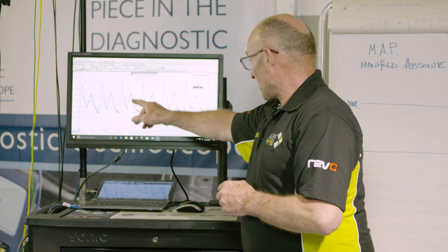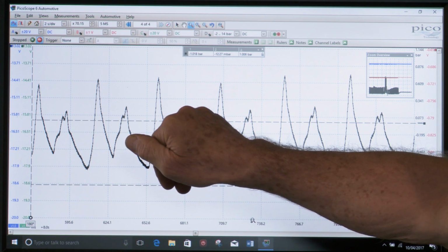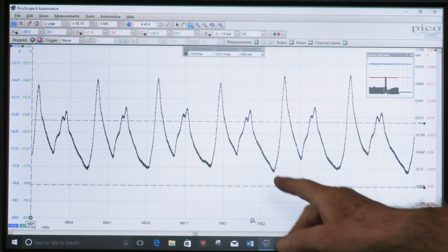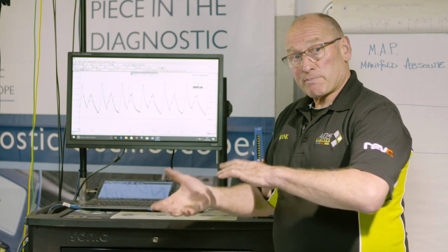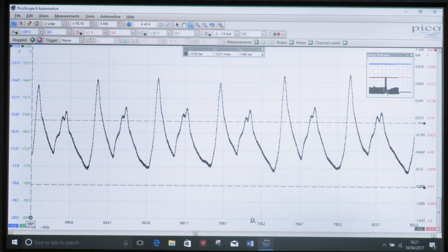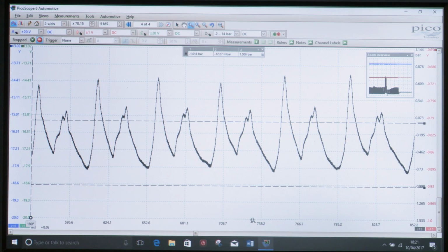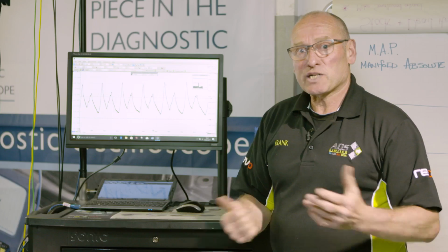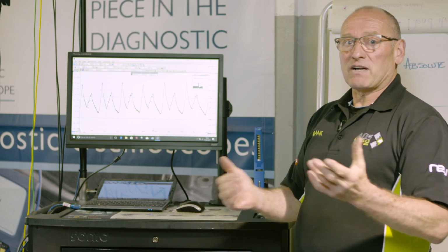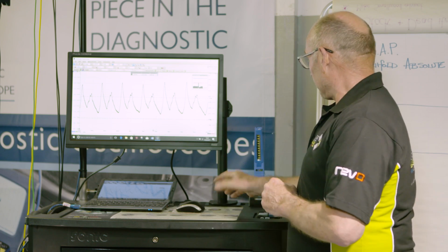The exhaust event here takes place. You can see there the reaction with the valve opening and closing. And we get a much superior suction. High engine speed, closed throttle, pressure differential now is much greater in this zone than it is there. We traditionally call this vacuum, and we would expect about 25 inches of mercury, thereabouts, minus 300 millibar, 0.75 of an atmosphere, below atmosphere. And we can measure it.